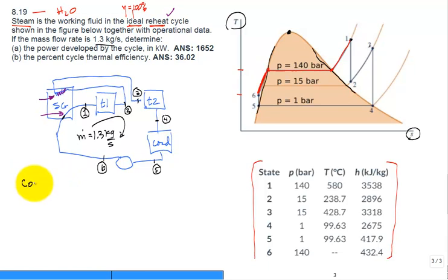So I would just say, how many components do I have? And then what is my Q, kilojoule per kilogram? And then what is my work in kilojoule per kilogram for each component? And so I can start with maybe the first turbine 1, go to the reheat. Do not forget the reheat. Easy to forget the reheat.